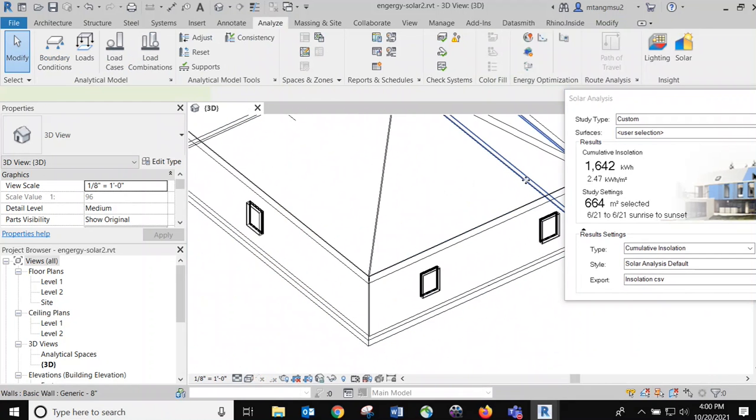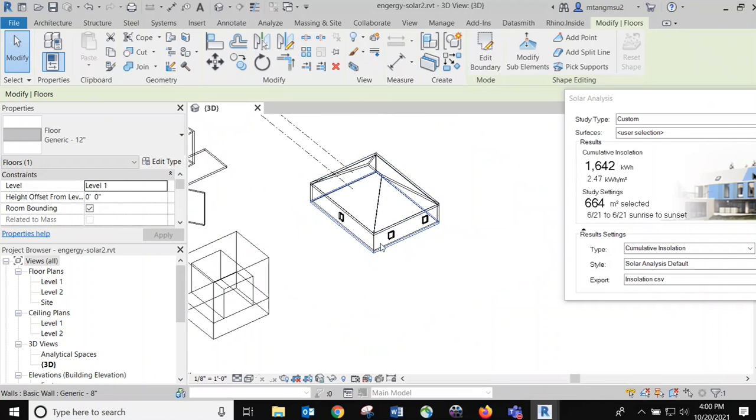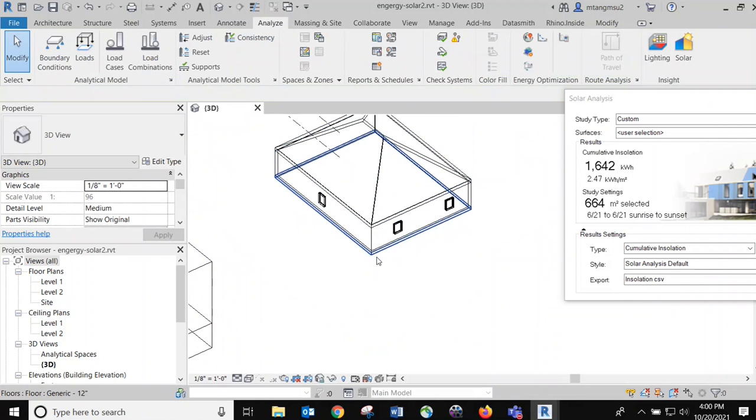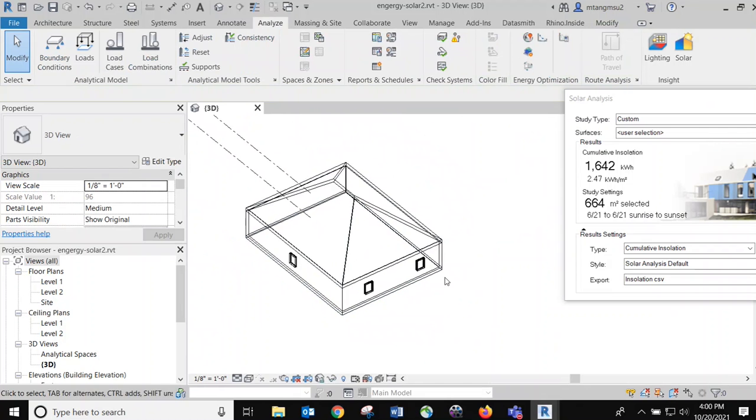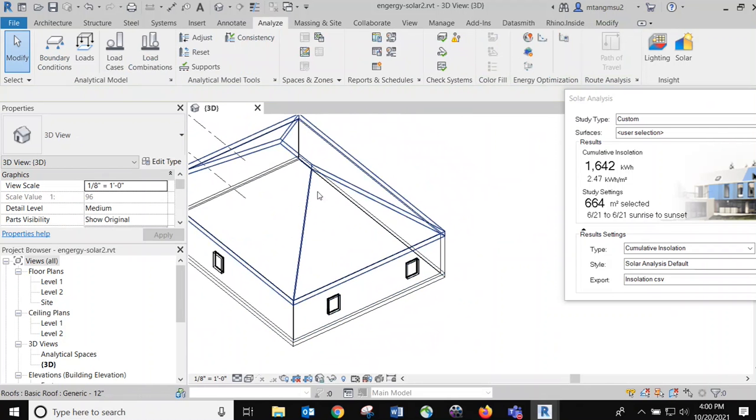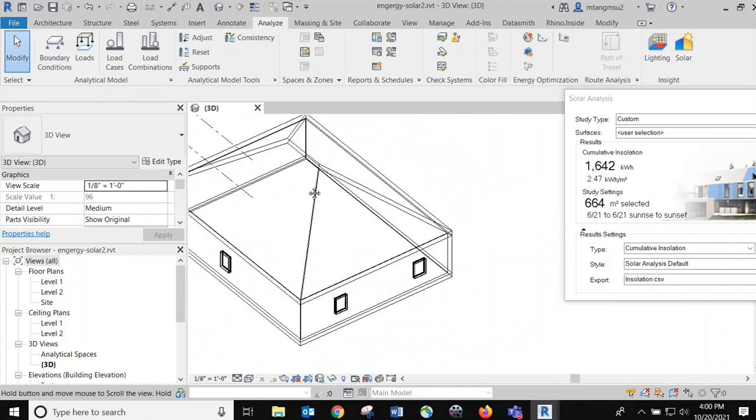So this is the floor at the bottom, right? If you recall, we have to create a volume, like a sealed 3D volume. So you must create something like a floor. Otherwise, it's not an enclosed volume. Okay, so I have a floor, I have wall, I have roof, everything is there.